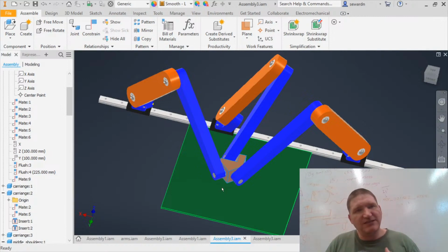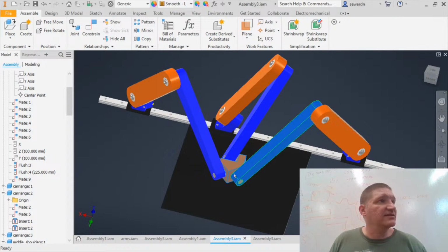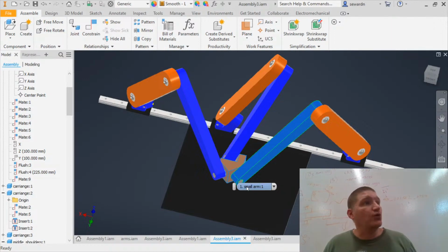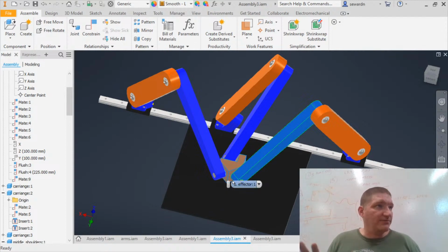Anyways, the leverage, even the dynamic forces don't get too high, and these carriages, I've been told, have very low play and have torque ratings up to about 50 foot-pounds. Way above and beyond what I would need for whatever forces I'm going to put on this. And I'm not going to put that much force on it because I know that this is a squishy robot. The end is going to be defined by these long arms, and the rigidity drops off the longer you get. So I'm going to try my hardest to keep the weight down.